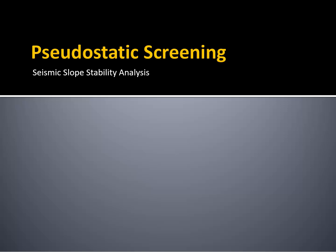Okay, continuing our discussion of seismic slope stability analysis. In the previous video, we saw an overview of how earthquakes can reduce your factor of safety, and we showed that with the very simple pseudostatic analysis you can add a kW term, which represents an increase in the forces driving failure, and how you'd go about updating your calculations for the factor of safety.